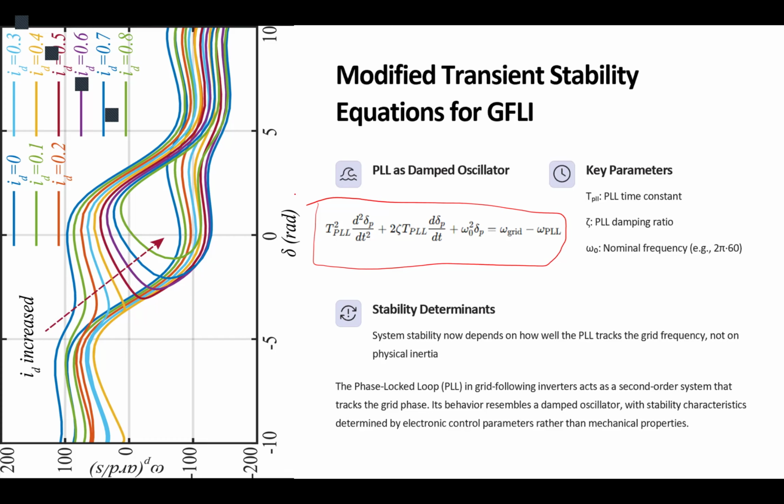And if we have a higher T, as you can see in your system, we have a higher inertia. So the system is resisting against the change, and with a higher time constant it's not easily changed by any variation at the output. Is that clear? Let me explain it again, I wanted to make sure that everyone is clear on that.